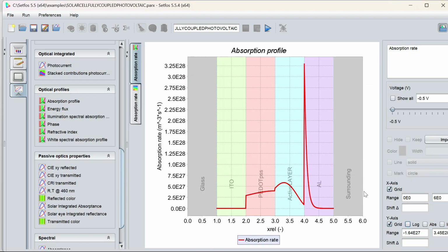For the optical absorption, you can see an organic photovoltaic cell consists of a multi-layer structure with layer thickness of the order of the wavelength of incident light, which is shorter than the coherence length of sunlight. Therefore, OPV is an optically coherent device. This gives rise to interference effects inside, which can be exploited to increase the maximum photocurrent by carefully tuning the